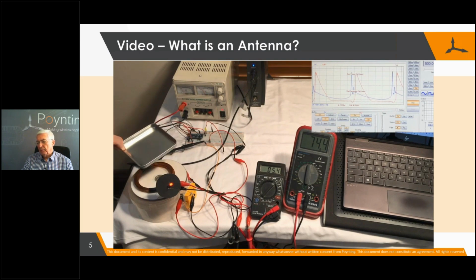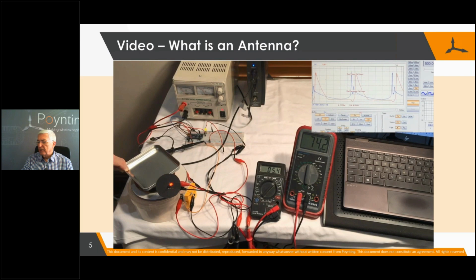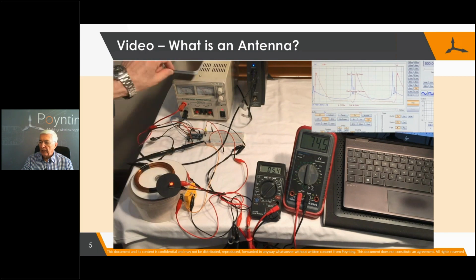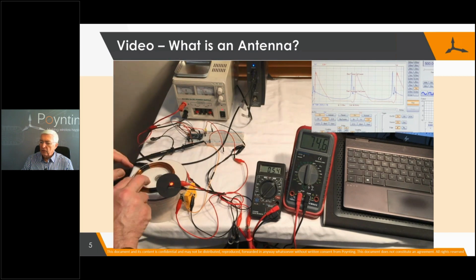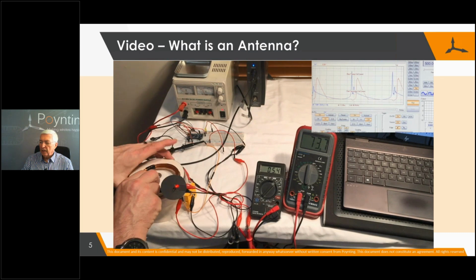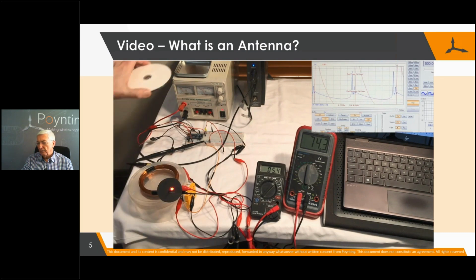So inside a building, you will find reflections. Now watch when I create reflections. Notice that I've not put that in between the transmitting antenna and receiving antenna. I'm merely causing reflections. So what do you gain when you have an outside antenna? You gain not having reflections inside the building and not having to go through a brick wall or a concrete slab.